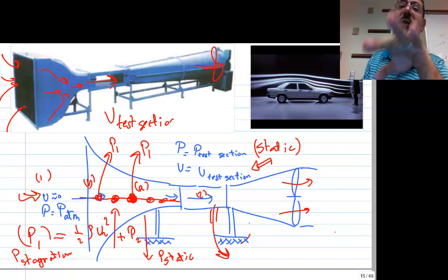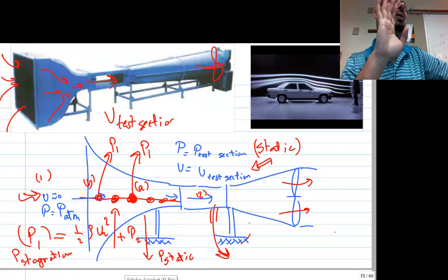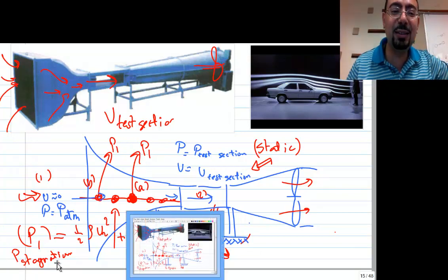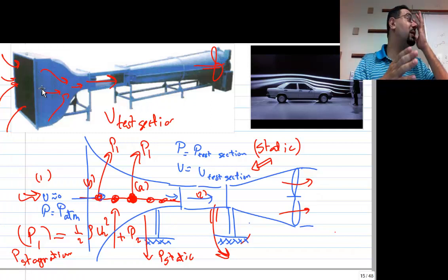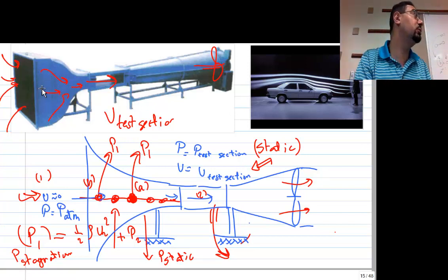That's the confusing part. Let's not think about this. Forget about this part. Just think about the inlet section. During the inlet section, P stagnation remains the same because you take that kinetic energy, you take that pressure, put them together, it will shoot up to its stagnation pressure, assuming nothing is lost during that journey.